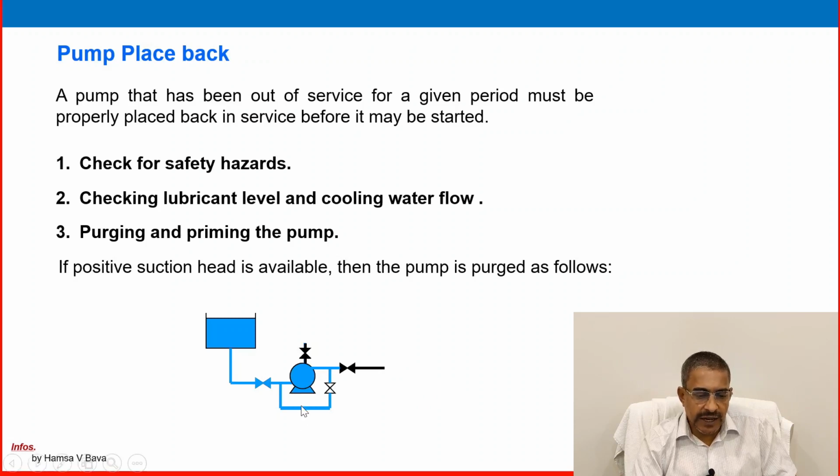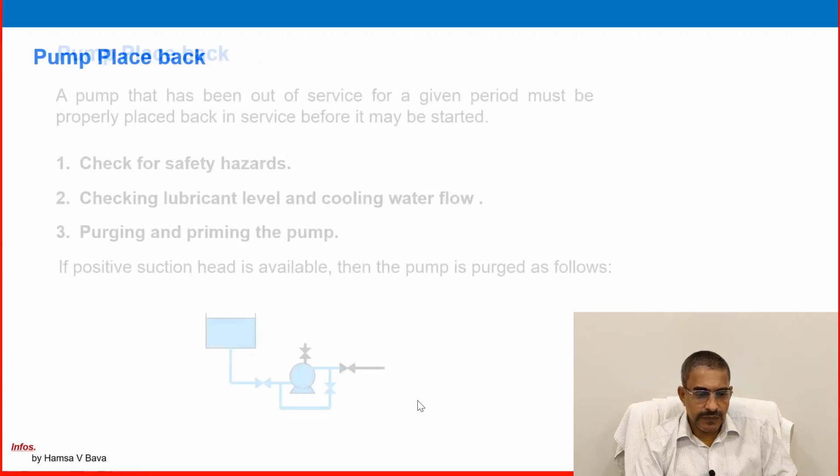Some pumps are also connected with a drain line. I showed that in an earlier picture. You also have to open the drain and release the contaminated water or liquid. Then it is filled with liquid. Now you can start the pump. Now the pump is ready for starting.